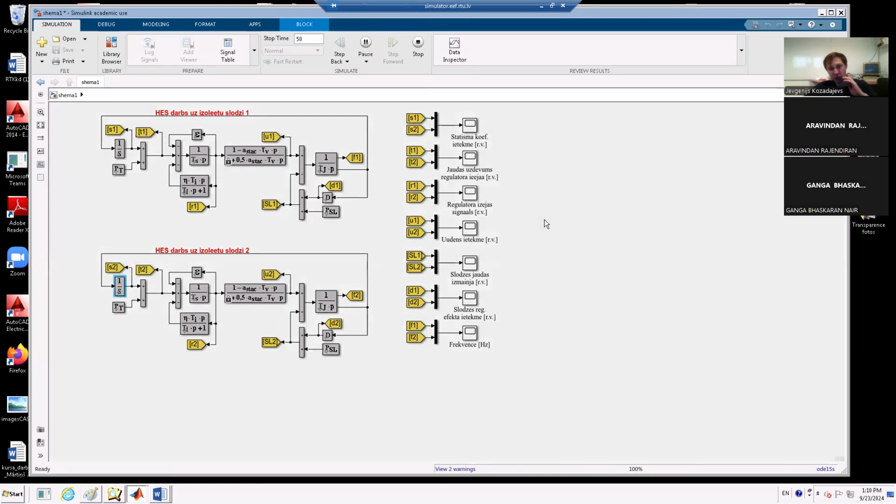Okay, I especially made a big difference in inertia. In other words, if we have more inertia, it means that all the processes go slowly. As a result, the system reaction to a power outage is lower. The reaction speed is lower. As a result, the frequency drop, the decreasing speed, is lower.